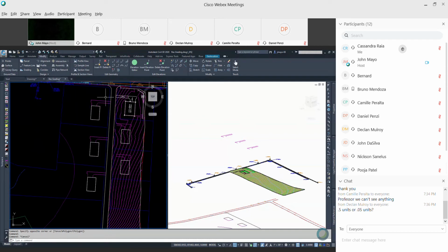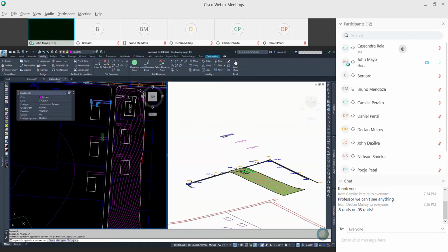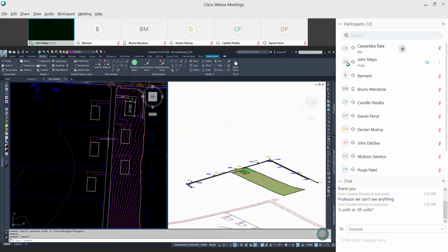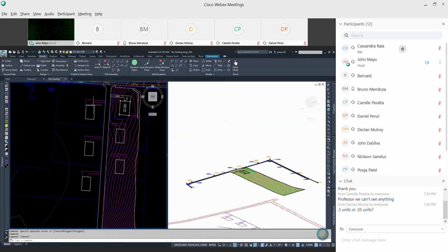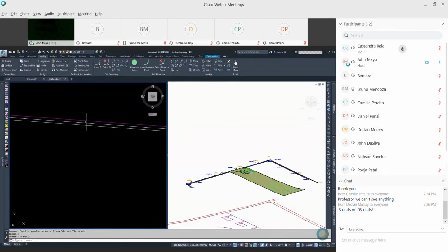So I'm going to set these guys to elevation 0, 2. So if by chance you work with any MicroStation information, that might be a useful tip for you, especially if you have a problem flattening MicroStation geometry. All right. Little trick.